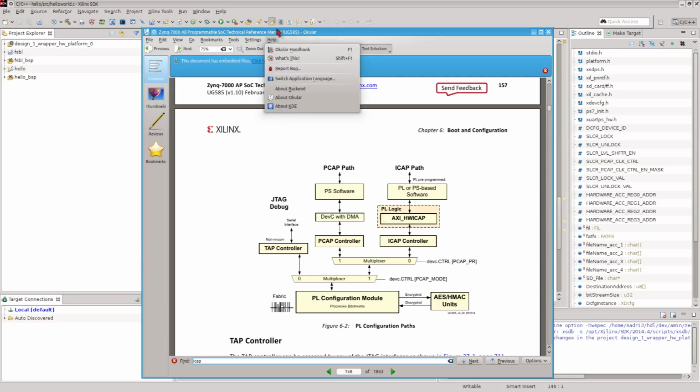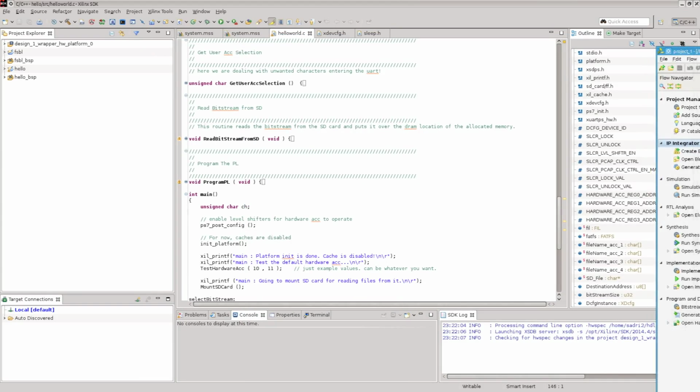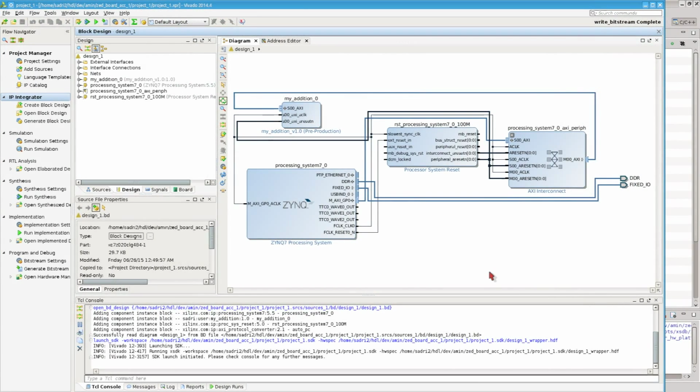What I do, as I told you, is I have these 4 accelerators, and the addition is the default one. For the ZYNQ Vivado project of this one, I have created an equivalent software development kit application, and inside that I have created my whole design, which is executed on the ARM host.